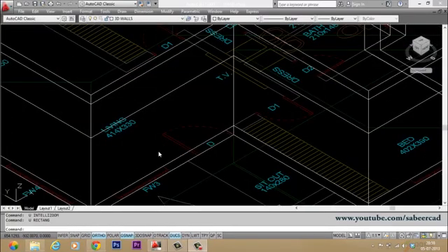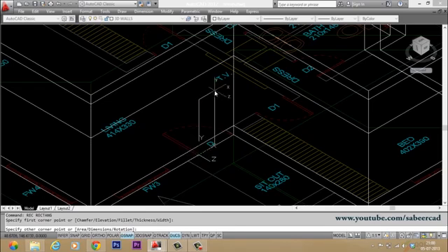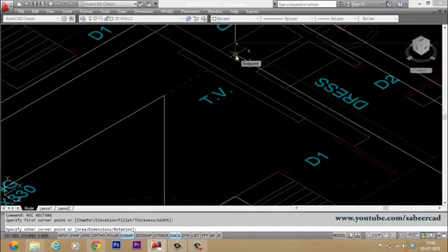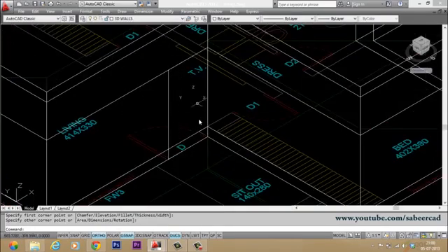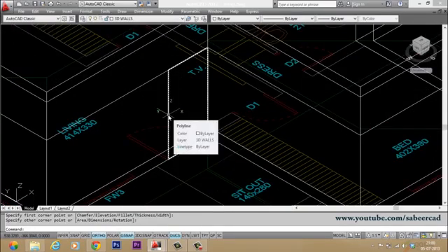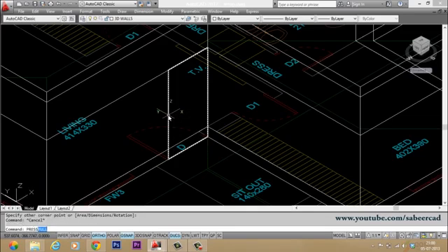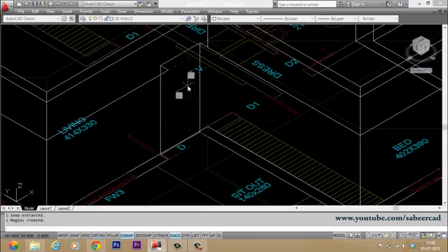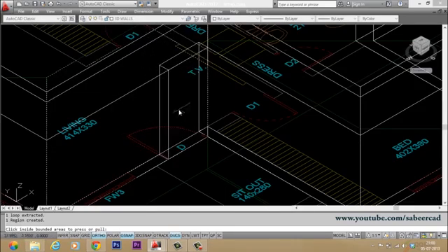Now let's move on to the door. I'll make a rectangle which has got the size of the door. So I gave the rectangle command and I want the door to align with this face. So I'll take the cursor onto this face and that face got highlighted. I'll click one corner here and the opposite corner is going to be here because this is 1 meter, which is the width of the door, and the height goes up till lintel. So you have a point here, so you can just click there. Now you have made the profile for the door. Now this can be readily press pulled the way you have done before. You can again give the press pull command and you can just select this profile and you can drag a surface inside. Now you have made a cutout here.